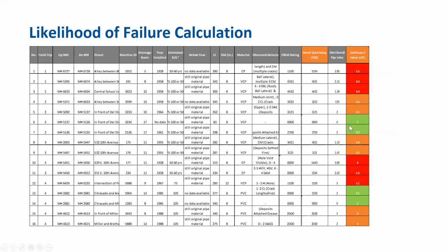So now, really getting into the whole risk assessment, the first step is to calculate the likelihood of failure. And we heard about the likelihood of failure, the LOF, in the previous presentation that Lani shared. But I just wanted to give you an idea of what we had to develop for the city. We put together a matrix, which was developed with formulas to produce risk scores.